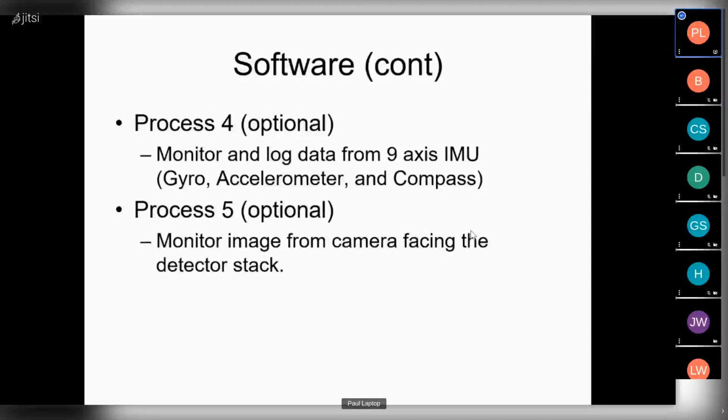Okay. Yeah, one of the next things I was going to try was doing some testing of the detector in the arena and see at what distance I can detect. Tuning that resistor in the voltage divider is a trade-off between sensitivity and speed. You can use a fairly cheap op amp and a photodiode and probably get a lot better results if you find you've got a limited dynamic range.